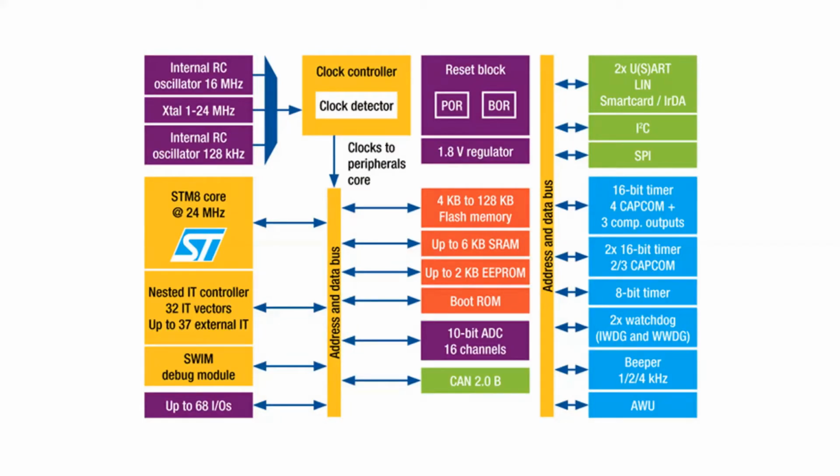Then you've got RAM, which, as many of you will know as well, is volatile storage, which means you need to apply power to it for it to keep the data stored in it. And the RAM is where your program is executed from. So when you turn it on, your program moves from flash into RAM, and then from there, the microcontroller core can read off what it's supposed to do.